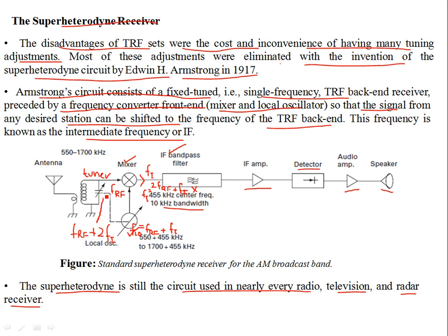So what I'm saying is, instead of FRF, you're going to tune into a frequency, because the antenna is going to transmit all the frequencies. Although your tuner is tuned to FRF, we still need a bandpass filter ahead of the mixer, such that if such a frequency shows up over here, then the difference of this frequency with the local oscillator frequency, you see, is again Fi.